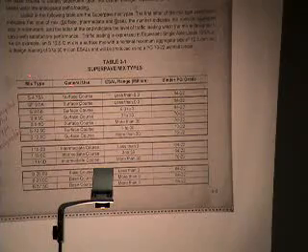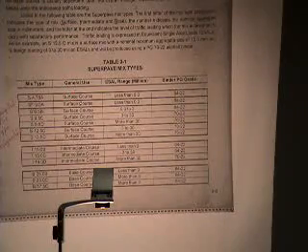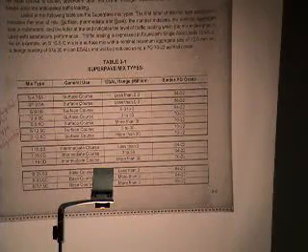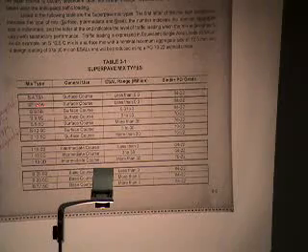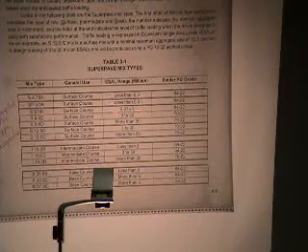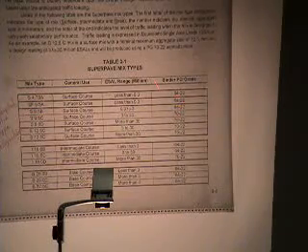The reason you're concerned about the surface is that's where the rutting is going to be, rutting potential is going to be the greatest. So on our lower traffic mixes, like on A and B levels, we use PG 64.